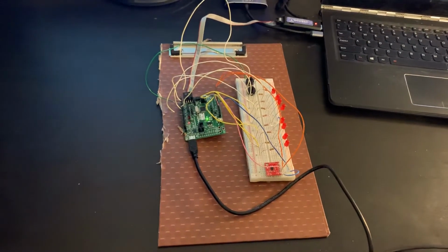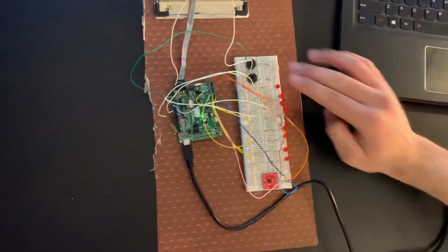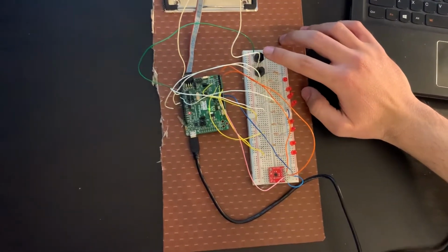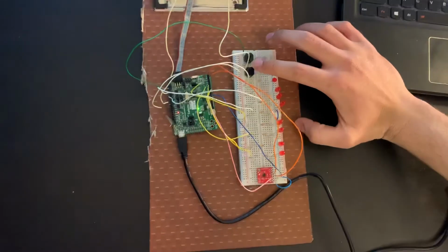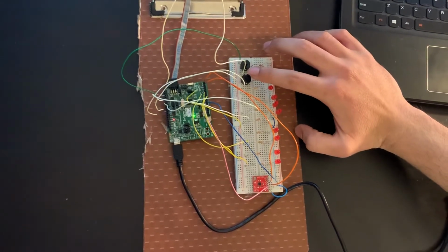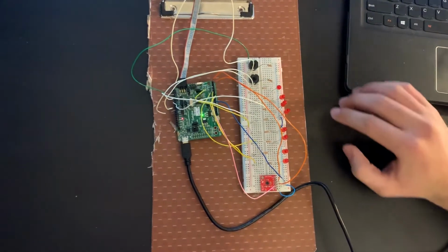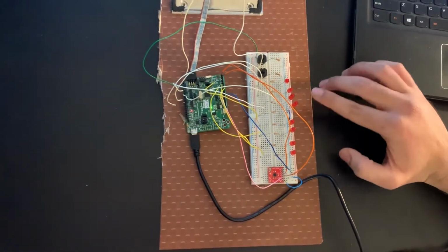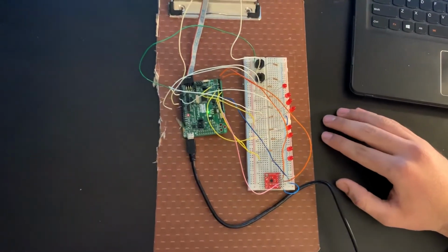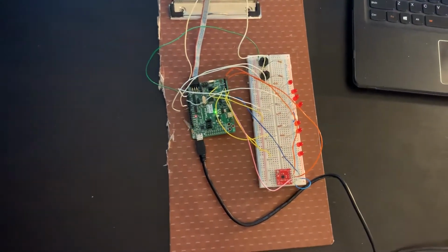Now to explain my system. It consists of 8 LEDs, 2 buttons, and the accelerometer. The first button is used to toggle between on and off. The second button is used to switch between mode 0, which measures the angle on the x-axis, and mode 1, which measures on the y-axis. Now for the LEDs, there are 8 LEDs that are used to demonstrate the BCD values. For the x-axis, I used channel 4, and for the y-axis, I used channel 5.